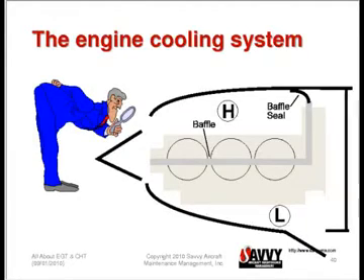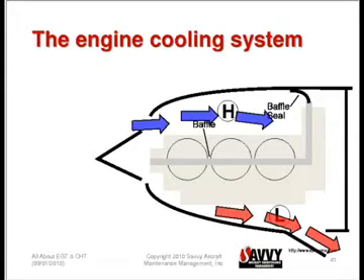Cooling system, just to make sure everybody knows how cooling systems on these airplanes work. Almost all of our airplanes are cooled this way. The way the cooling system works is that we allow ram air to enter the cowling on the top side of the engine, creating a high pressure area. We allow air to exhaust out the bottom, either through a fixed opening in the cowling, or adjustable opening cowl flaps, to create a low pressure area below the engine.